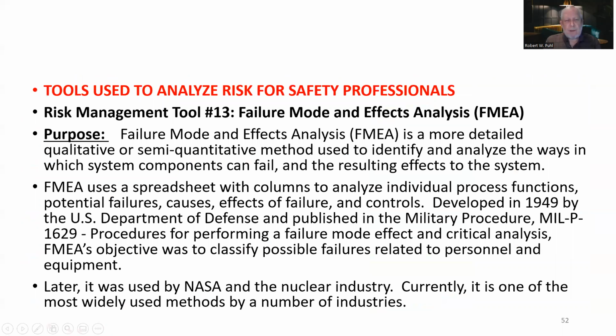This is an interesting one. Now, failure mode and effects analysis is a more detailed qualitative or semi-quantitative method used to identify and analyze the ways in which system components can fail and the resulting effects to the system. FMEA uses a spreadsheet with columns. Hey, there you go, a novel idea. To analyze individual process functions, potential failures, causes, effects of failure, and controls.